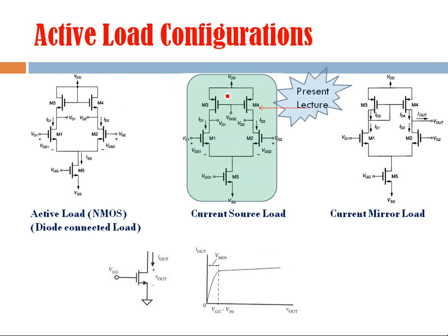You know that in this particular configuration the gate terminals are connected together, and the gate terminal is biased with some gate voltage. This gate voltage will decide how much current will pass through the device. So this device is used as a constant current source, so how much gate voltage, that decides how much current will flow here, and not only this gate voltage but this drain source voltage will also decide its configuration, so how it is working.